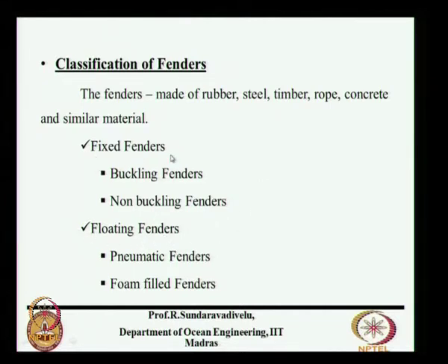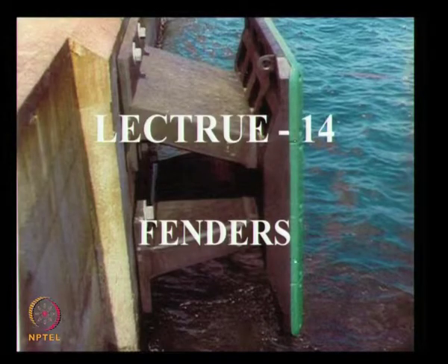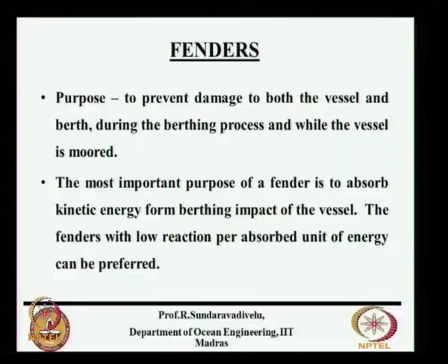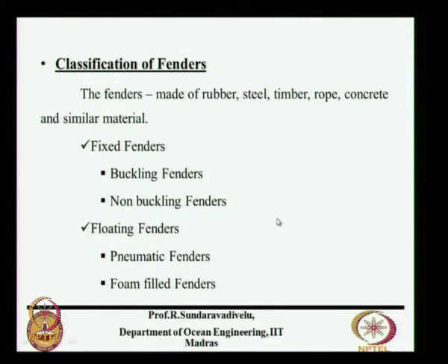Whereas in a fixed fender you have to have a frontal frame. If you see this particular slide, we have the frontal frame like this. This frontal frame should be very close to the low tide level, and this top level should be above the high water level. So, that is the main purpose of this frontal board height. This height will increase when the tidal variation is very high, that is in case of fixed fender. The weight of the fender also should be taken by these bolts. But mostly we use nowadays only fixed fenders.